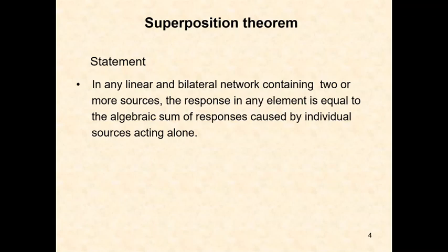See the statement. In any linear and bilateral network containing two or more sources, the response in any element is equal to the algebraic sum of responses caused by individual sources acting alone. I am repeating the statement again: in any linear bilateral network containing two or more sources, the response in any element is equal to the algebraic sum of responses caused by individual sources acting alone.